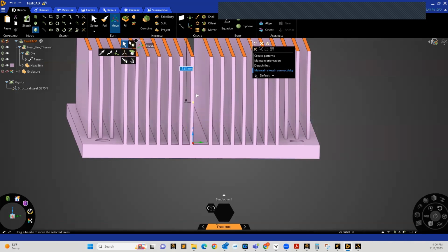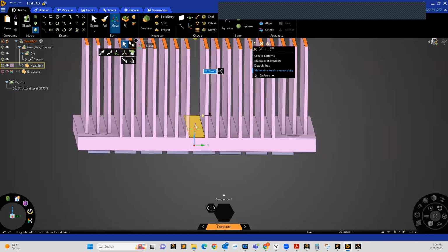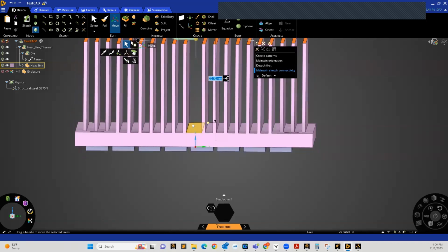And so you can see as I move up and down, I have this little yellow ball next to my cursor. That little yellow ball is where I'm actually setting my reference. If I scroll down and highlight over this bottom surface here, or I guess I should say the top surface of my heat exchanger, and rotate this a bit, I can see that if I click this surface, that's where it's going to select my point of reference. And so that's what I'm going to do, I'm just going to left select this top surface here.